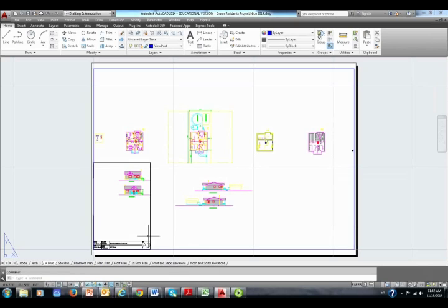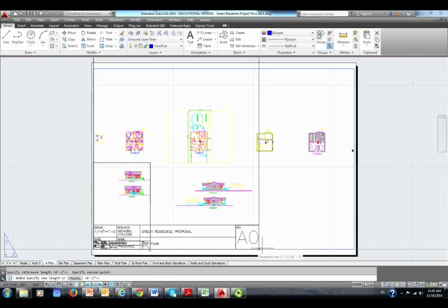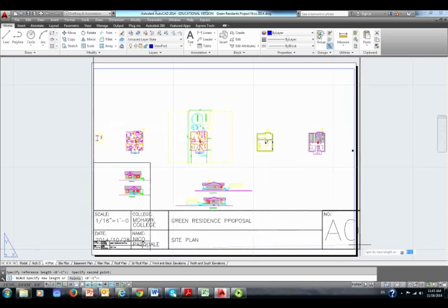Undo, undo. I'm going to do it again because something has gone wrong and I don't know what I did wrong. So let's try it again. Scale. I'm going to take everything this time, the entire title block, hit enter, specify base point, R for reference, specify length. I think we need to pick up this point again. And then new length. Yes. Okay, so now I know what I messed up.